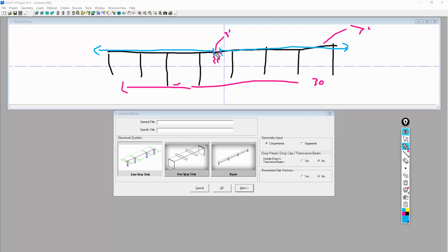And after those two tendons or sets of tendons along the pour strip are stressed, we come back several days later and we pour this back. And we have reinforcement passing through here that's going to take care maybe of the flexural demand across this location. And so we're going to assume that for our model, we're really just representing the final stage of this strip, kind of the as-built condition of the strip. And we're capturing that through this particular model.